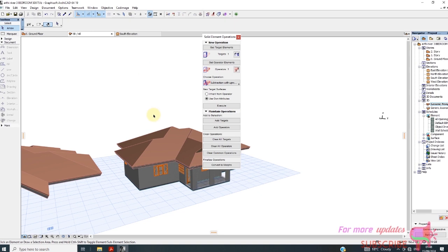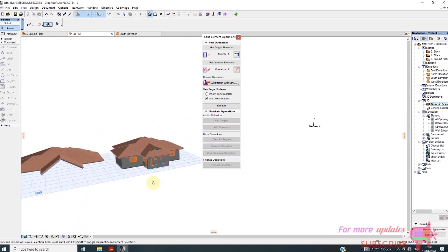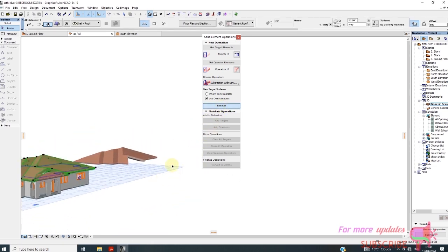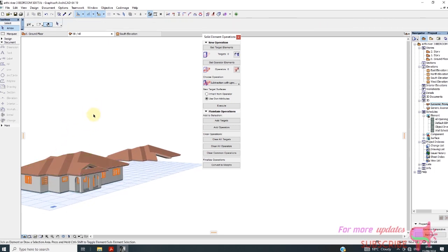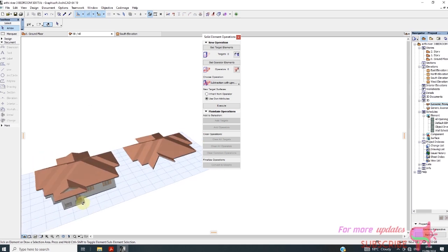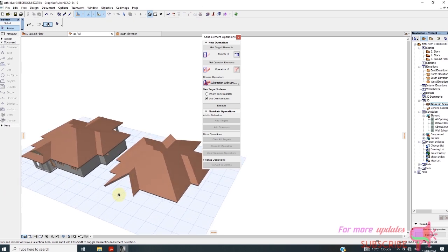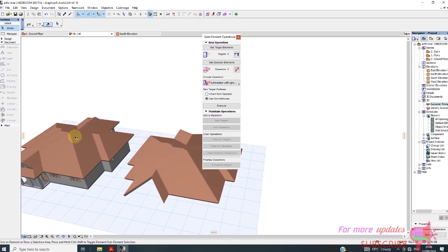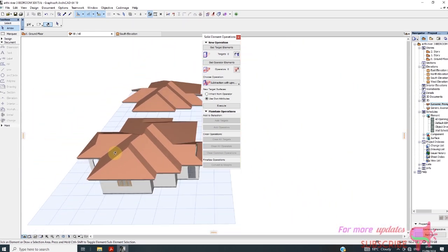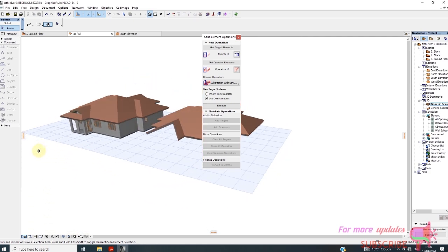So if I go to 3D, I can just hold shift to rotate, then execute. Again, now this time you're able to see what we have just done. So in the same manner, we can just create another Dutch roof at this point or at that point. Can create as many roof vents as we want.